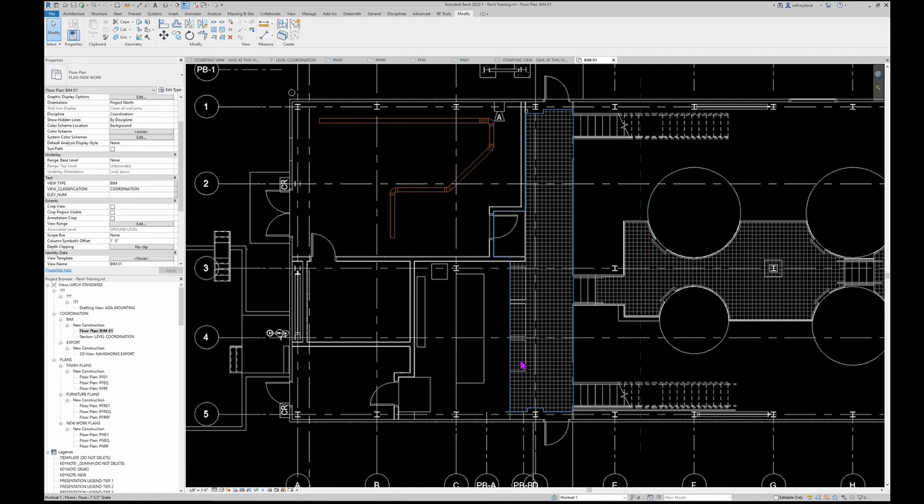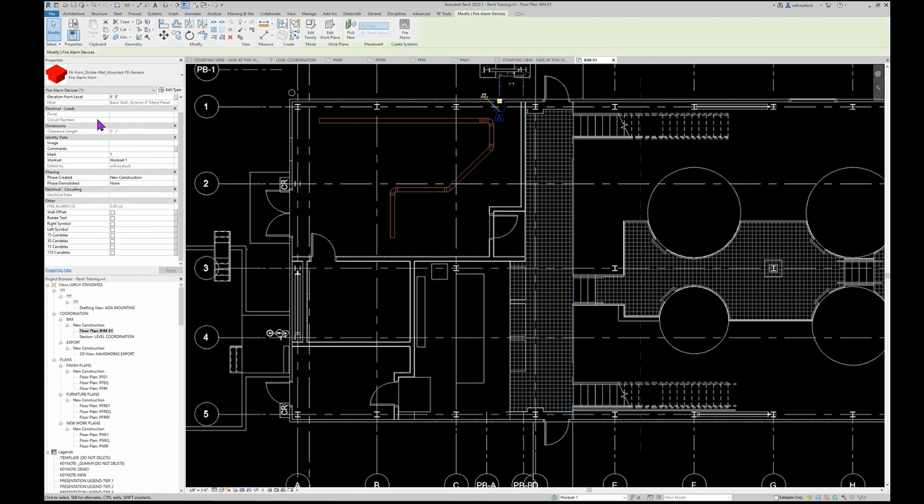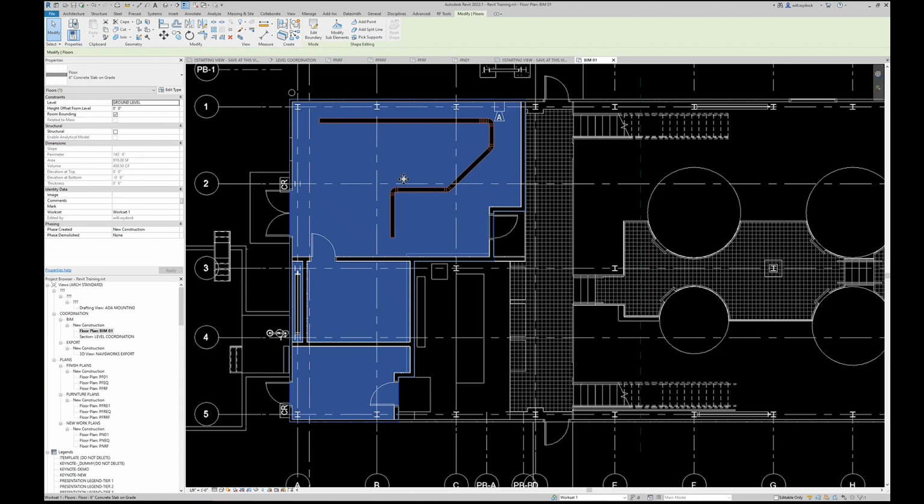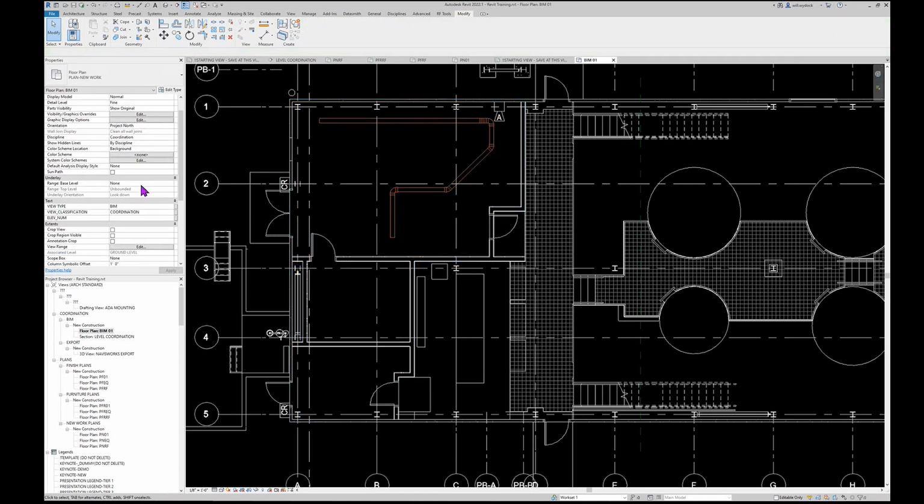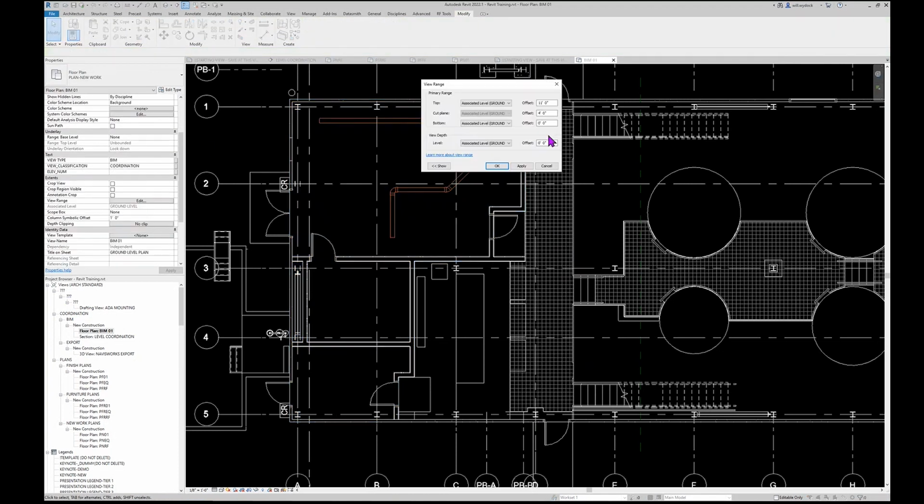So if you try modifying a cut plane to come this high based on your architecture settings, you're going to have your doors mess up. So it's very important that you understand this. So this is set to 6'8", so that's right up there, right at the top of the door. Now, this would show up here, but I don't need to go the full range that this view is set up to. This view range is set up here to 11.